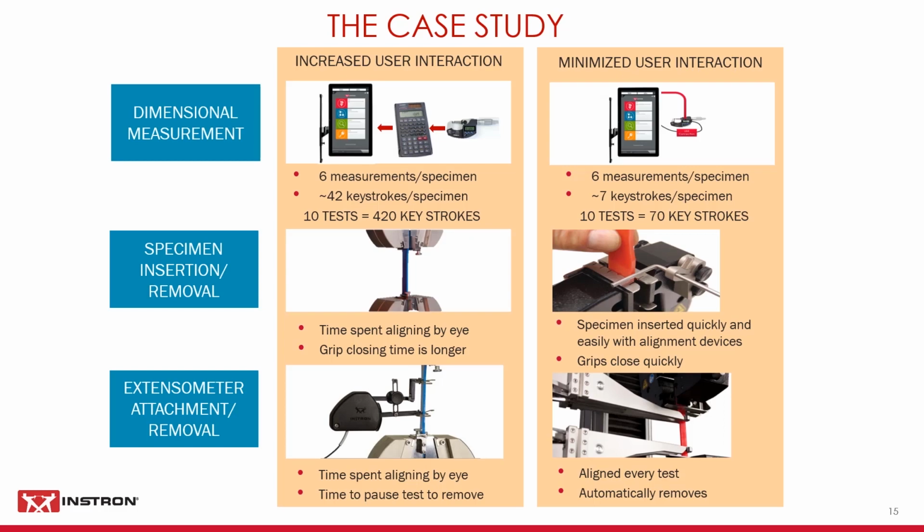In this case study, the test time was approximately 1 minute. When compared against each other, the system setup on the right showed a 38% reduction in cycle time, which is equal to 80 seconds saved. If you need to test 100 specimens during a shift, the setup on the right can save 133 minutes of time. For more brittle materials, or if you're able to run faster test times for your standard, you can see over a 50% reduction in cycle time with the ideal system setup.